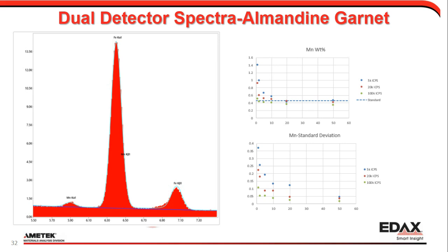And if you have a dual detector, well, you have the same size, you can do it in half the time. There's nothing here you can't do with a single detector. It's just a matter of the time it takes. So this is similar to what we did with the floor tile sample, where we have a nice flat sample and we can just add the spectra together, get better statistics, and do math on that to increase our reliability.